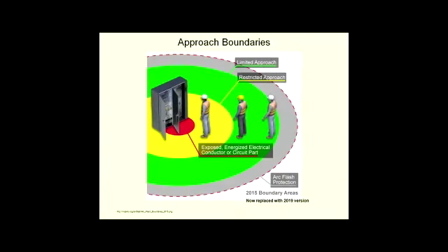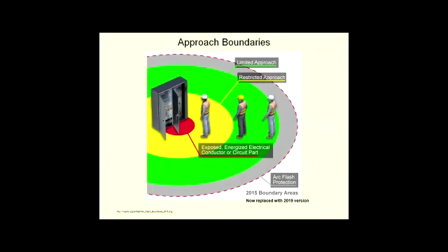The distance can vary because the equipment power rating and the capability of causing a certain strength of arc flash can also vary. So in plants or commercial environments, you're going to see boundaries of different distances depending on the strength of the equipment we're using.